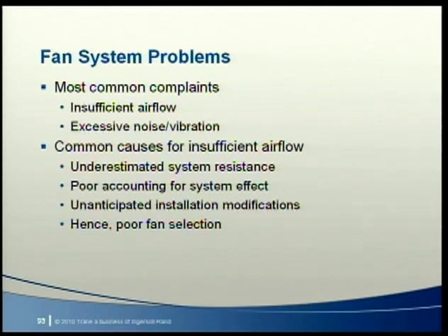If you rely on rules of thumb to estimate system total static pressure, you may find yourself increasing motor horsepower on many jobs. And architects always seem to want small equipment rooms. Tight spaces lead to less than ideal duct connections at the air handler. The resulting system effect must be accounted for during design or dealt with after installation.